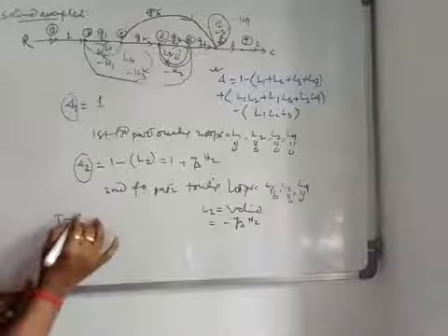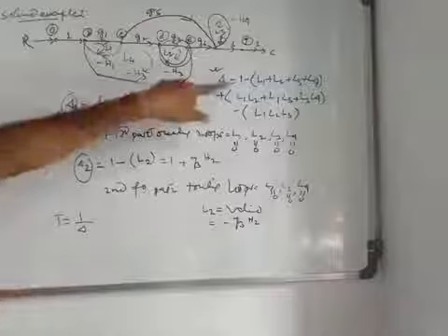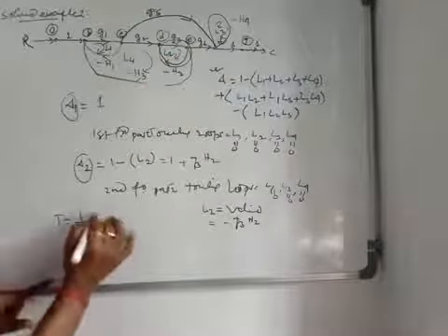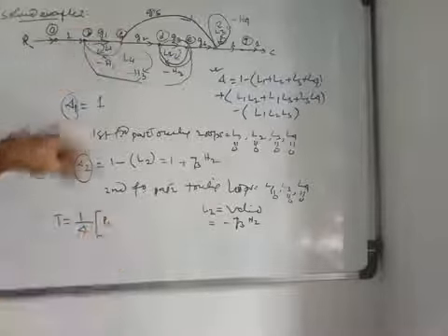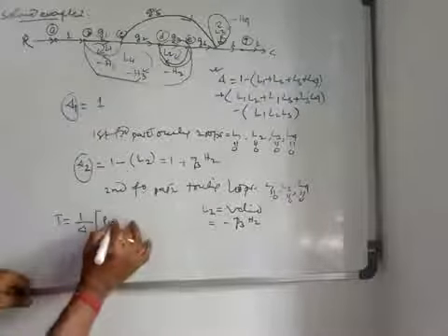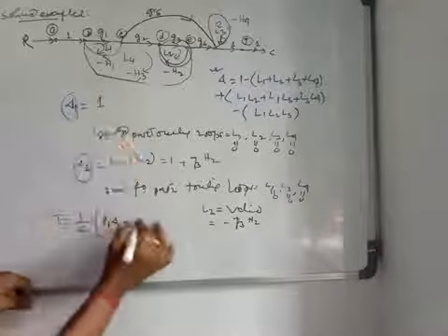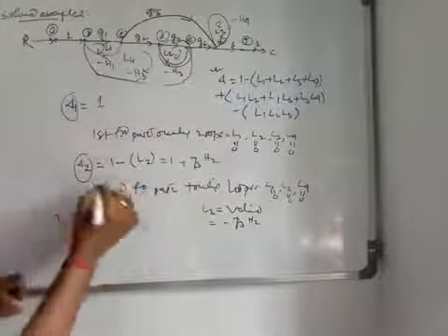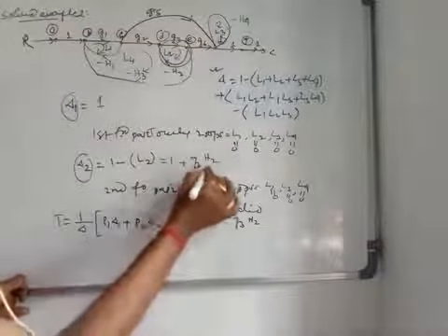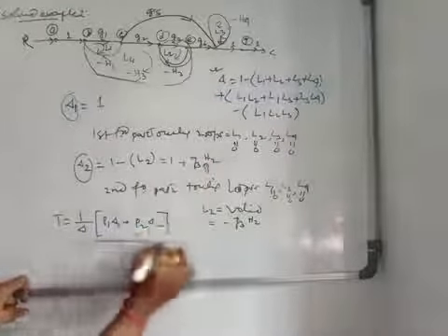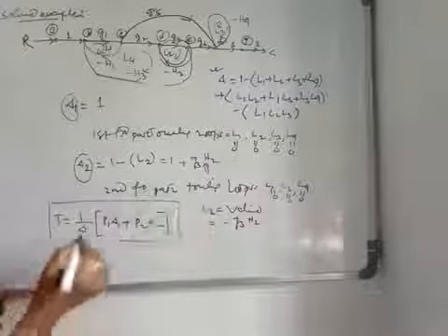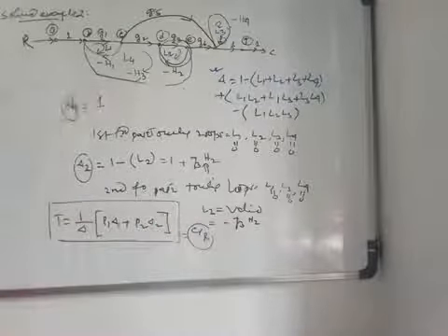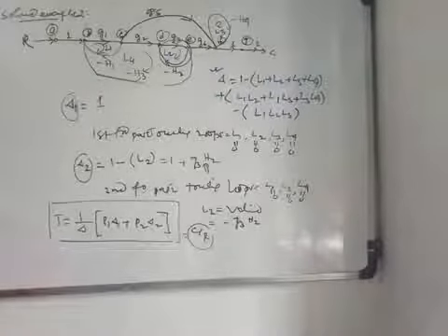So Q will be equal to 1 by delta, put the value of delta here. L1, L2, L3, L4 and all these values are known to you. We just put them here in the denominator. Next P1, the first forward path gain, you put here. Delta 1 is 1 here, plus P2, the second forward path gain, you put there, and put the value of delta 2, that is this, right? So this is the overall transfer function, that means C by R for this signal flow graph, right?